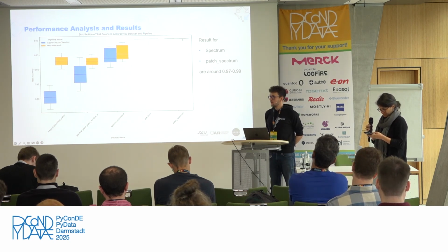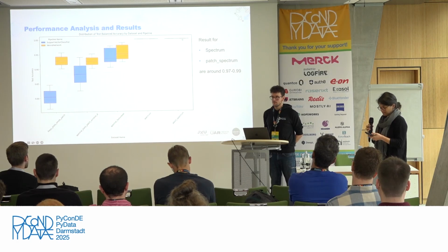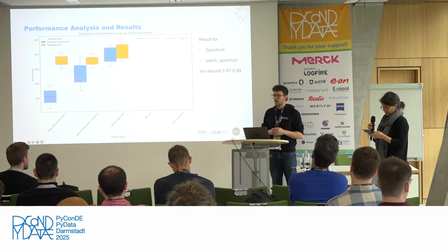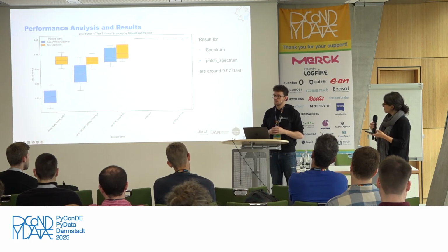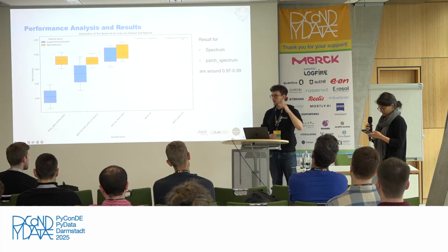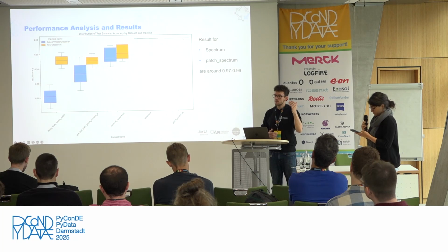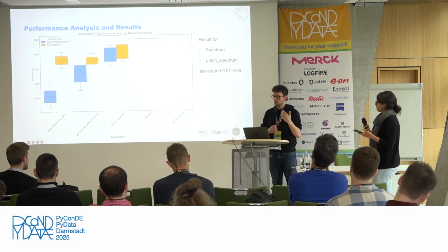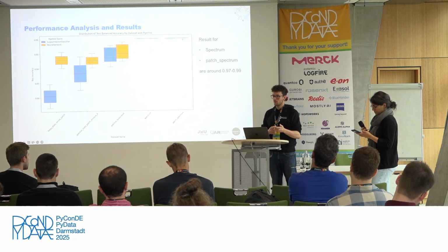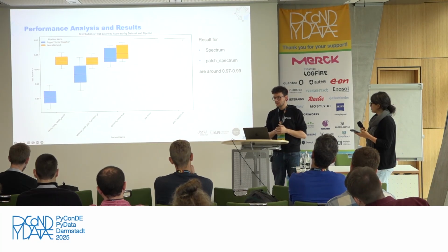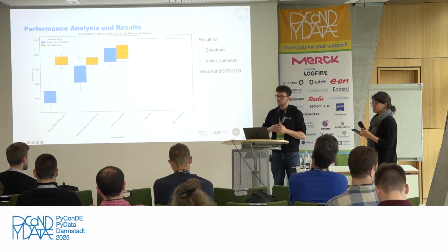Yes, we tried that in the initial experiment. It made a difference, but it wasn't too large, especially with the materials we tried, which was metal, some kind of metal. So those are rather similar. I, however, expect if you change the parameters of the material, so how thick the material is you are cutting, it might impact the sensor by quite a bit. Because for larger material sizes, you actually need a bigger flame, which likely introduces more noise and a different signal. That's why I said in the last parts of the slide, generalization really depends on a lot of factors, and it will not be easy.